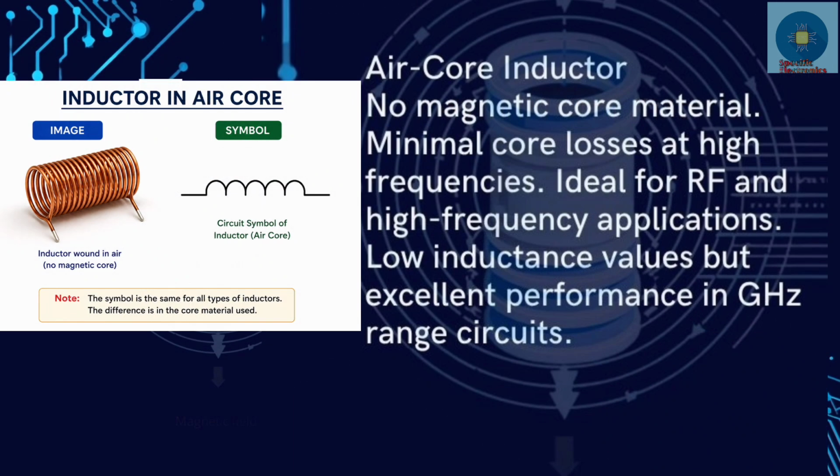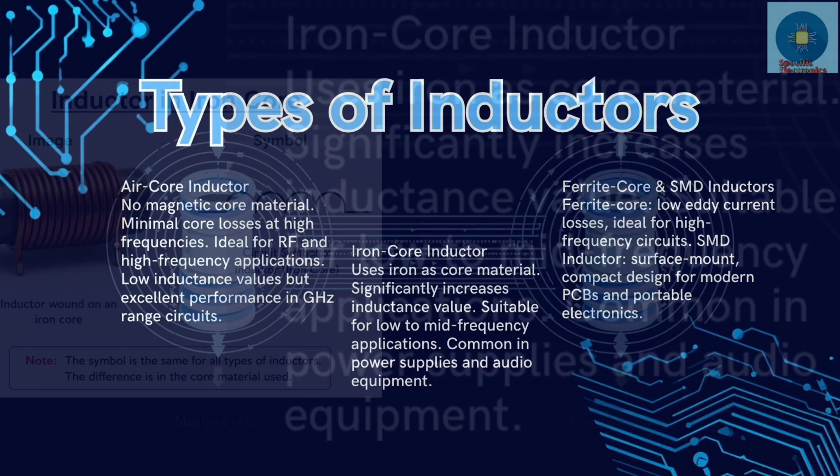First, the air core inductor. As the name suggests, this type of inductor does not use any magnetic core material. Minimal core losses at high frequencies. It's ideal for RF and high frequency applications. Low inductance value but excellent performance in the gigahertz range.